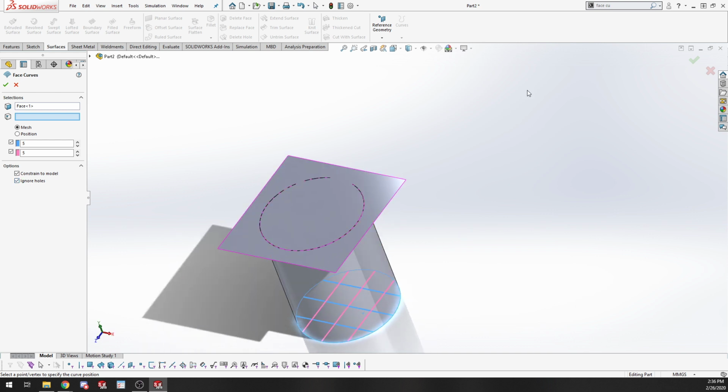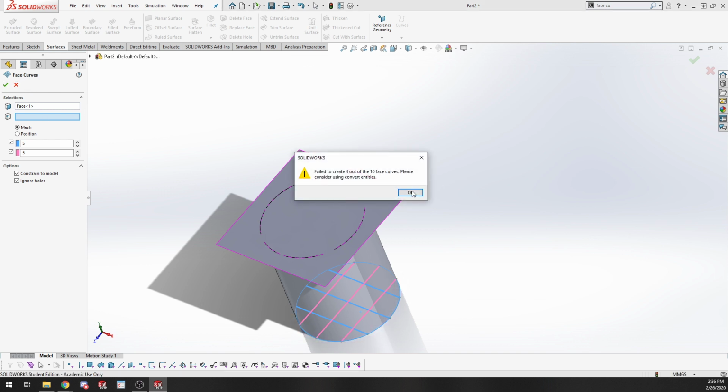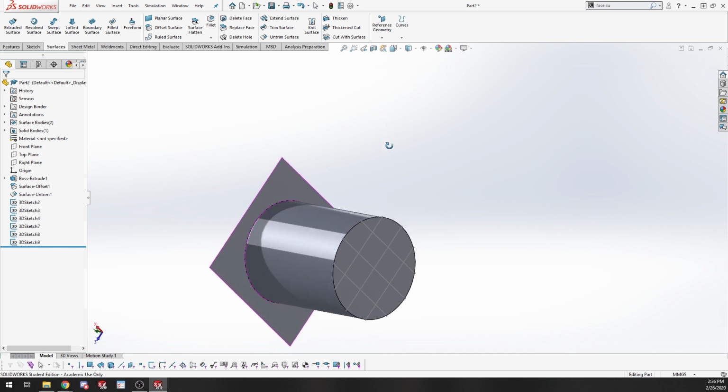If you're going through the face curves command, it's kind of hidden, so not a lot of people know about it. You can go through, click on your part. See if we still have that steering wheel open. We don't. Okay. So yeah, you can click on your face curves, you can actually see where SolidWorks is interpolating between for those surfaces, and go from there and say, oh yeah, this is all coming to a point here. I should cut that area out and remake it so it's a little bit nicer, and SolidWorks fits a nice surface into it rather than trying to get cornered in. I don't know if that really made a lot of sense, but that's kind of where we're at.